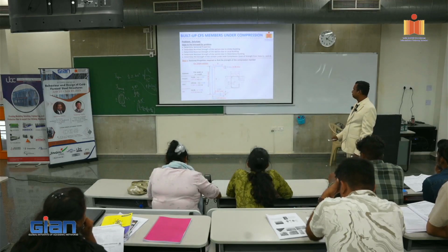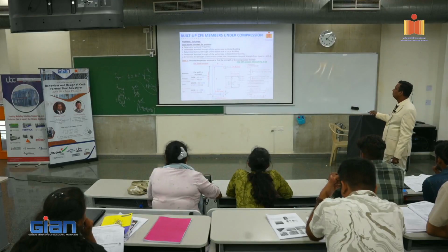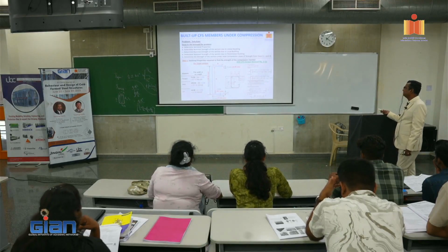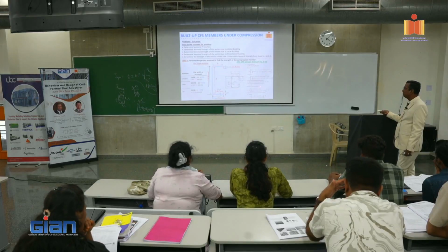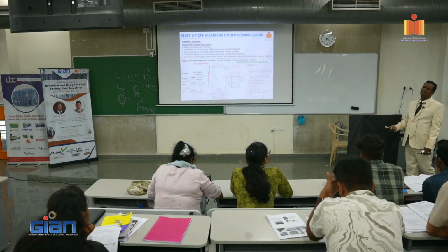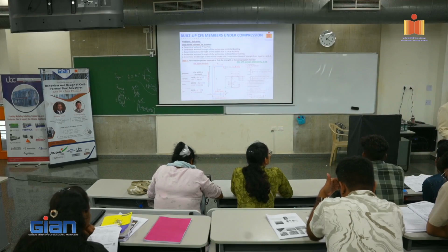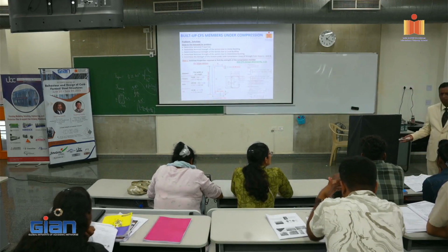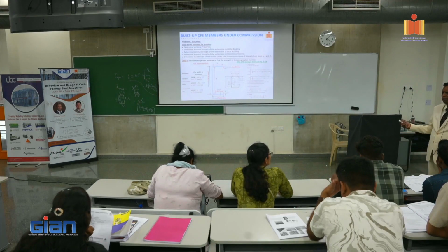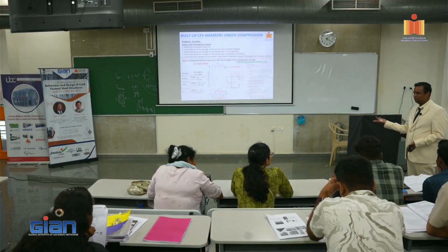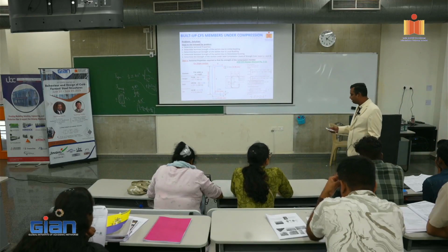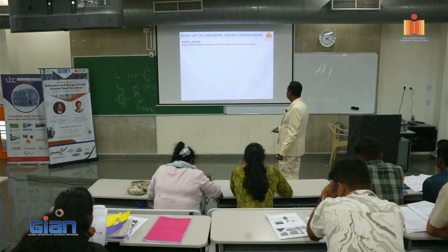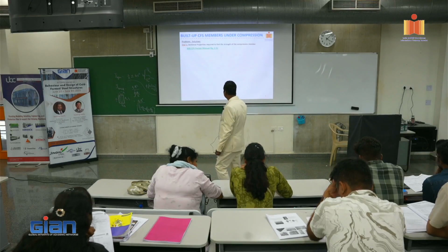Right? Now you go to the AISI CFS Design Manual, page 151, you get all these gory equations. It's not very difficult. It's just strength of materials equations. You can plug it in your Excel sheet once you have programmed it, or you have MathCAD, you put it in, you will get it. Piece of cake, not a difficult thing. Right? So you get the section properties.